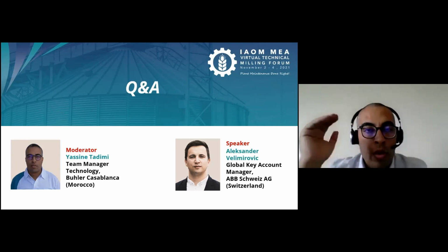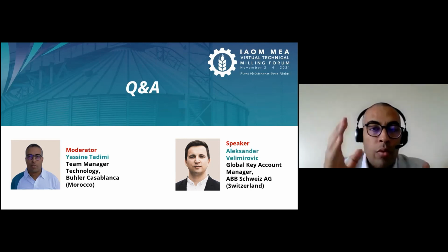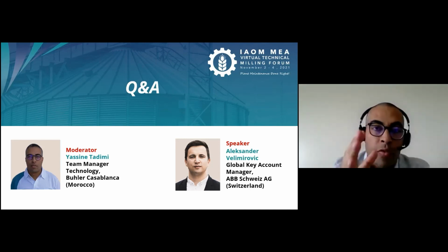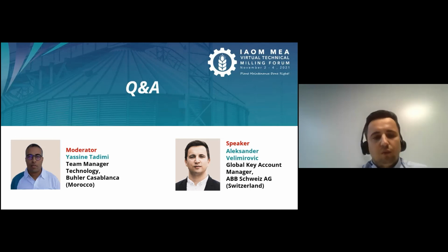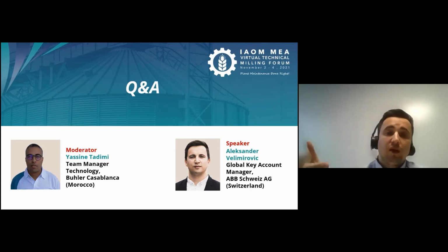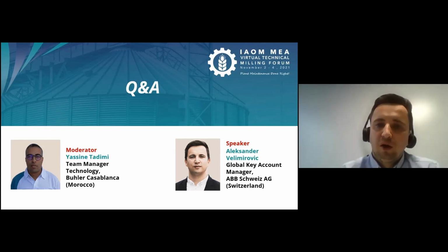But even if we go higher than the nominal speed, we should always be in the nominal range of amps that it's absorbing. It should not go up, otherwise we will damage the inside of the motor. Exactly. This is quite a rough and good statement, which I can agree with. If you have continuous torque, then you cannot go above the nominal speed. But if you have some margin, then with the same torque, the current is increasing for the field weakening. It's called field weakening operation.